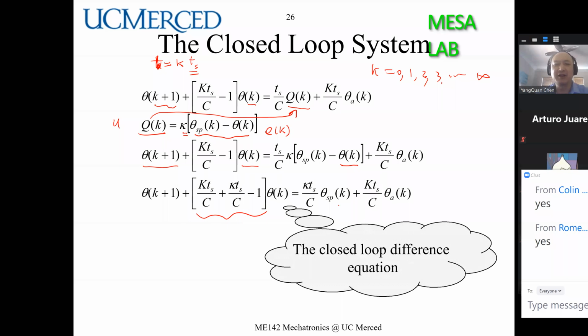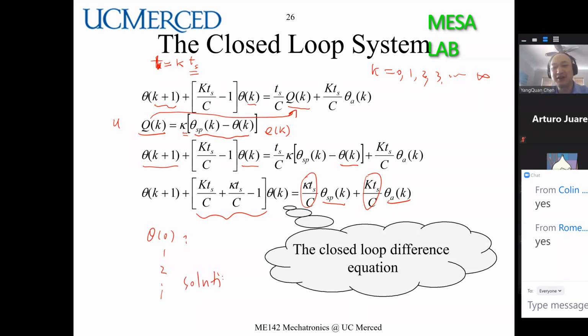These coefficients are all known. I want to understand what is my θ(k) given θ(0), then what are my θ(1), θ(2)? This is the solution, a discrete sequence. This is called the closed loop difference equation of θ.